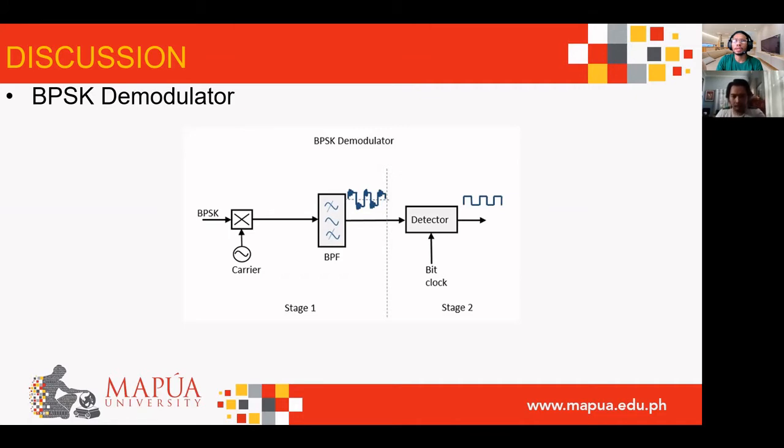In this process, the demodulator is recovering the original message signal, or the pulse signal that we introduced in the BPSK modulator. The band-limited message signal is recovered with the help of the mixer circuit and the bandpass filter, and the first stage of the demodulation gets completed.